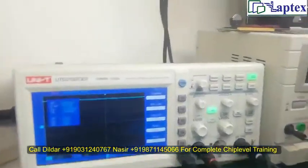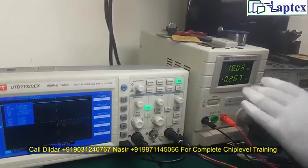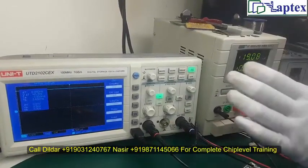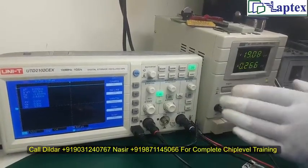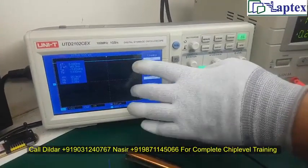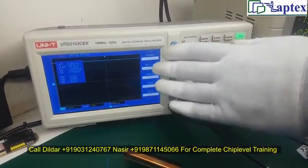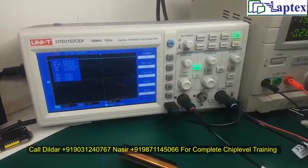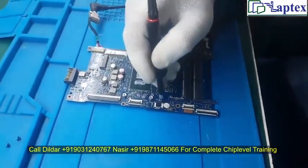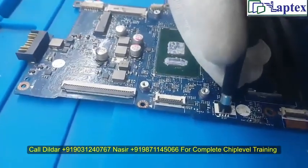signal this way, since my motherboard is on, and suppose your laptop is off as of now, and you are getting a voltage on the CS, and even after turning on the laptop the same situation remains, with no falling edge signal on the DSO, you can understand that your chip is not selected by the PCH, and the data output pin will be at high impedance, so there would not be data output.